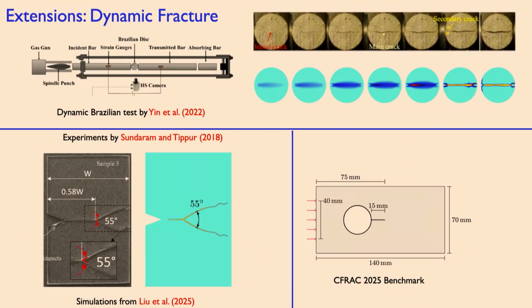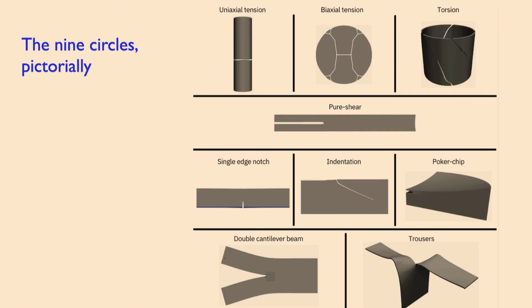So I was showing you simulation results. Some of those are new. For example, that biaxial tension result qualitatively resembles what you'd expect. Brittle materials fail that way under uniaxial tension. Under pure torsion, they tend to localize at 45 degrees. For pure shear, you will find experiments for that.